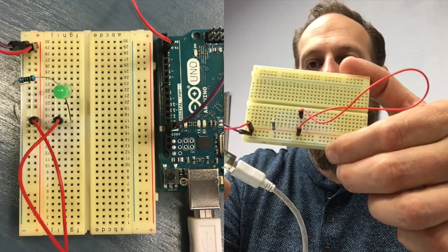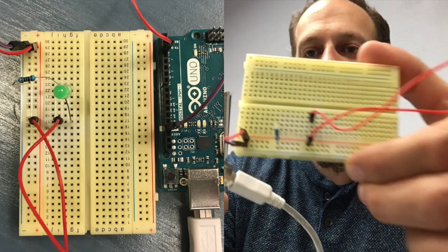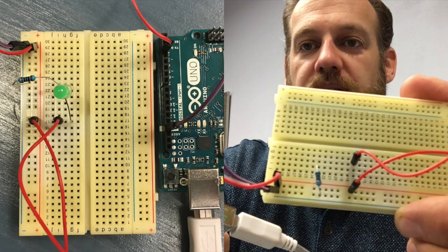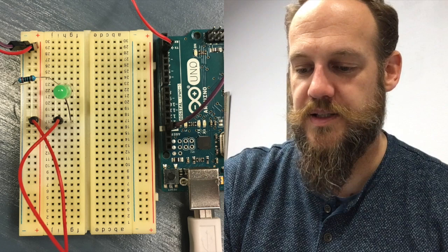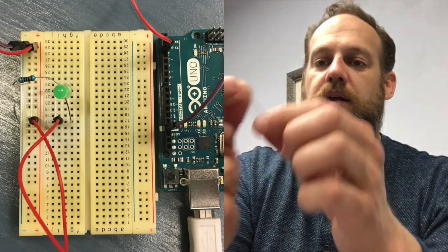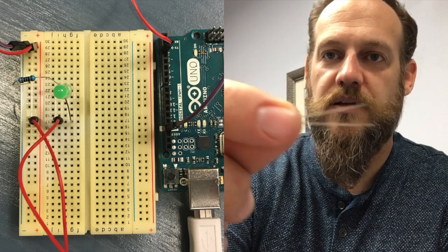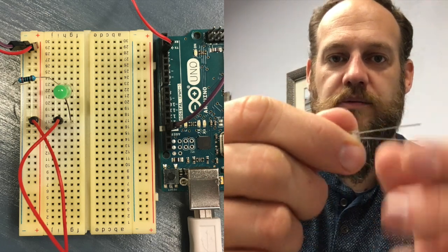in just a minute. You want to do this so that you're going to separate the pins on the LED. Alright, so here's how I do this. I take the long pin, remember that's the anode, I bend it up a little bit, and I'll bend it halfway down, so I've got this. And what that looks like, so you can see the LED on my fingertip, like that.